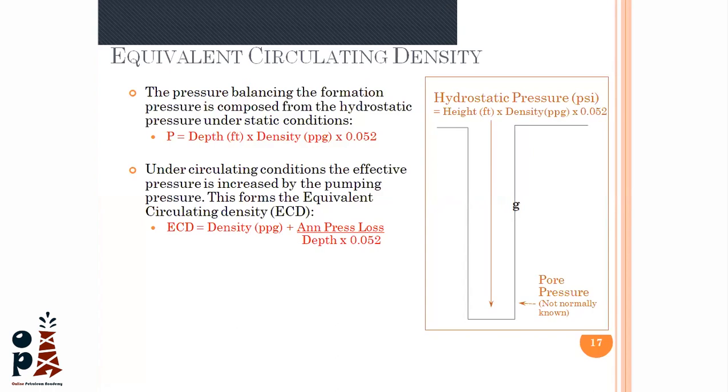So the mud will circulate. The mud will be circulated using the pump to elevate the cuttings. Just to clarify this point, we need to circulate the mud to take the cuttings out of the well. There are a lot of reasons to circulate the mud, but just say for illustration this one. So the mud will not stay static. The mud will move, will be dynamic.